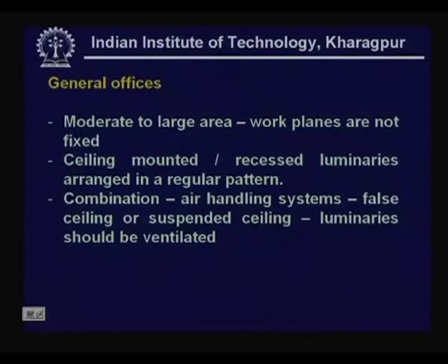And in fact, when the ceiling heights are very high, we adopt false ceilings in which these are recessed, and the false ceilings themselves are made with good reflectance levels, as close to pristine white as possible.